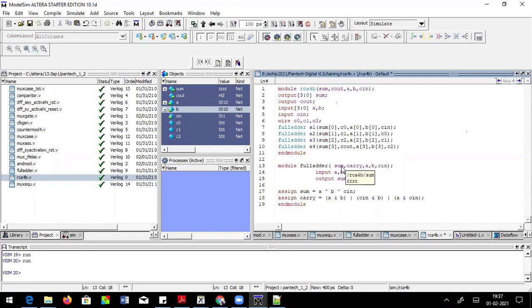While giving the input, can we make Cin as 0 first, or can we make Cin as 1, A and B as 0, so that we can check whether 1 is coming or not? We can give the initial input for the carry as 0. No, that's coming. That we have checked. A XOR B, XOR Cin, that's fine.